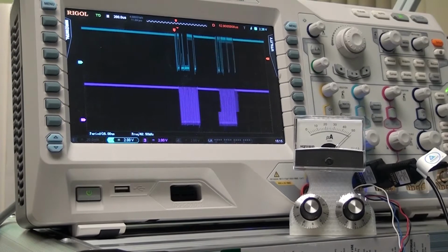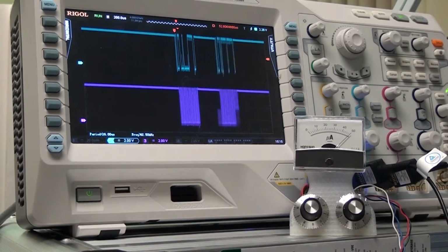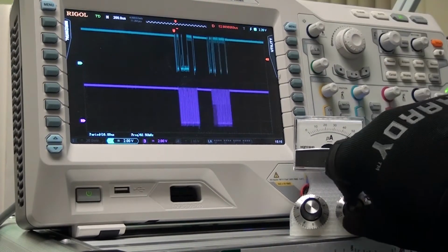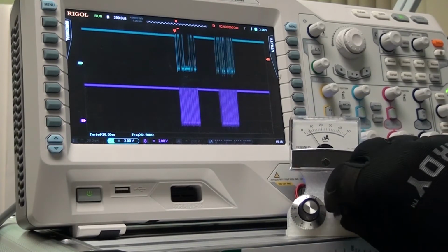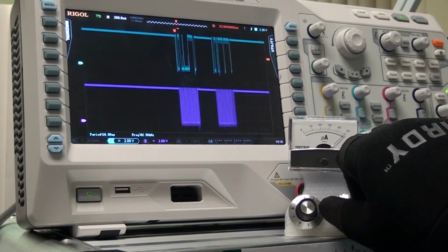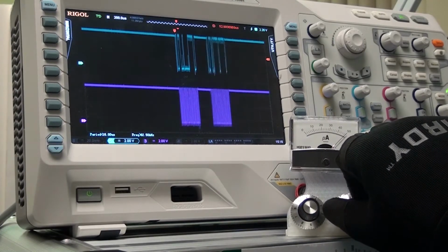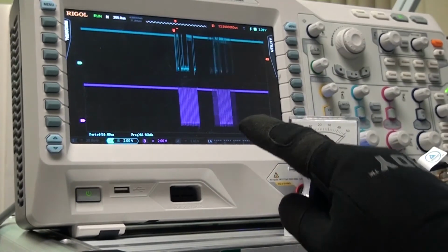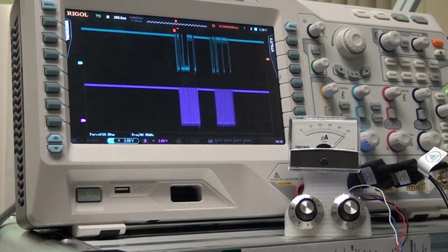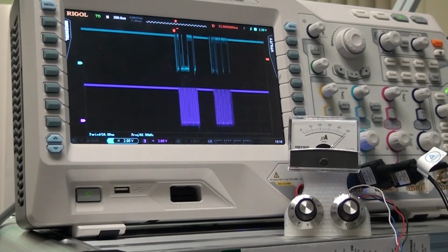Now in this segment you are going to see not only the reading of the ADC. Again, I'm at 0 going all the way to full scale, which is 255 or FF hex. You can see that the first signal is reading from the ADC, and the second signal is outputting to the DAC. So you see an input operation followed by an output operation on the I2C bus.